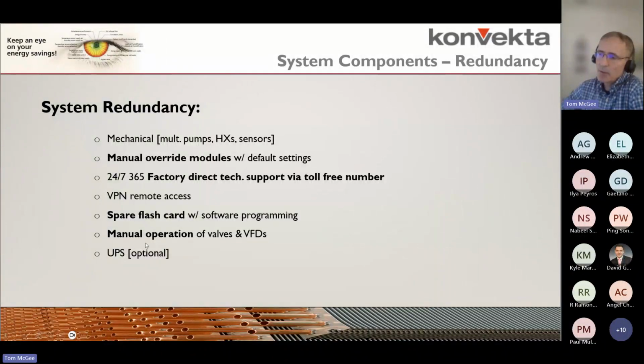So if we have heat injection to where our coil is providing 100% of the energy recovery and 100% of the heating functionality, then we always include a UPS to make sure that we can maintain power if we get a power bump. And a lot of that has to do with wanting to keep a stable communication with the BAS via that BACnet interface.